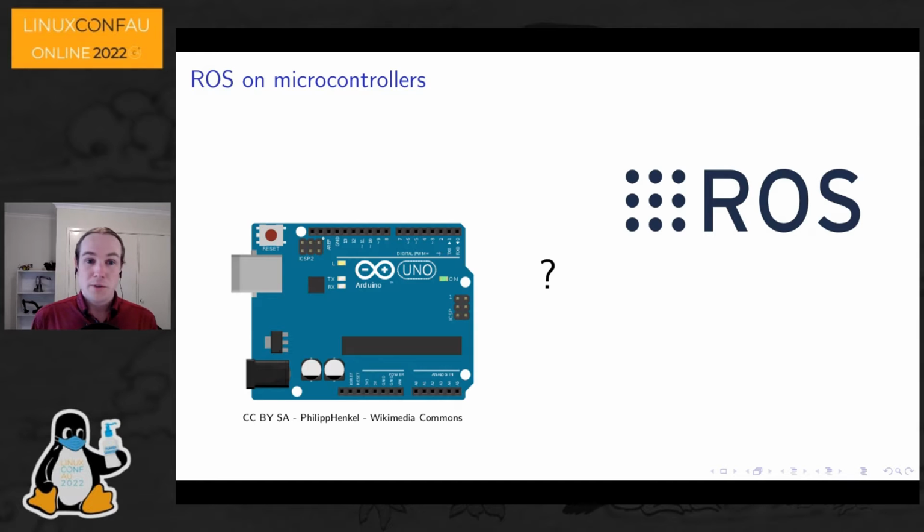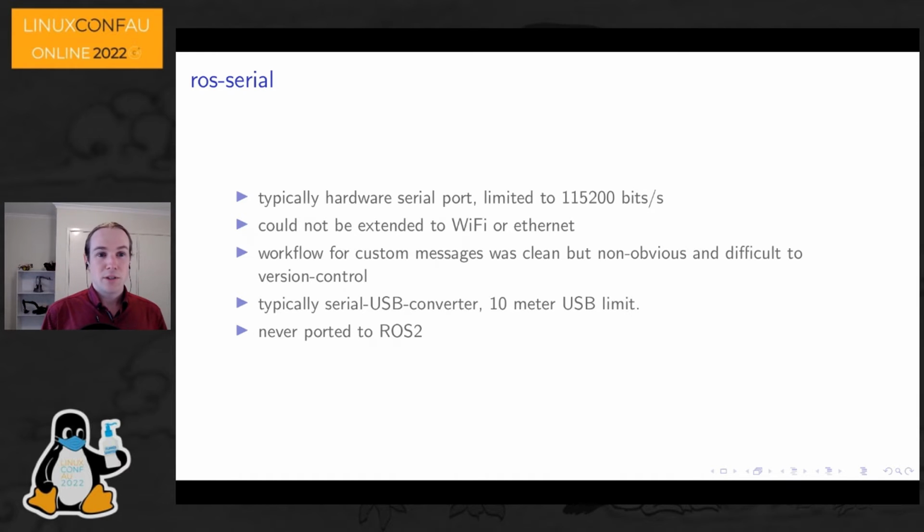Using an Arduino for an out-of-chassis experience for a robot was so common that the ROS community made a couple of compelling attempts at getting ROS to work nicely with microcontrollers. ROS Serial provided a generic host-side node that could be instructed by an Arduino to interact with a host-side data stream. The Arduino side library let you set callbacks to be executed when messages arrived and pack messages to be sent. Overall, it was very clean, but it was a very clean implementation for ROS 1 by the time ROS 2 came about.